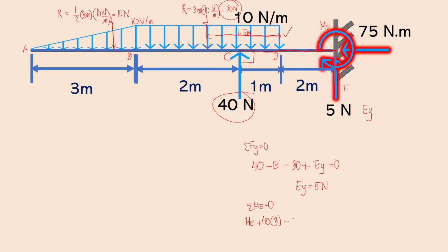And then, let's plug in our load, which is 30. And then, we will multiply by the moment arm. Now, the moment arm of this, toward E, will be this whole distance. Because this load forms a right triangle with the beam. So again, this is a right angle. And so this is the perpendicular distance from here to here. And so, that will be 1.5 plus 2 meters, because this is 2 m, as labeled here. And so our moment arm is 1.5 plus 2.